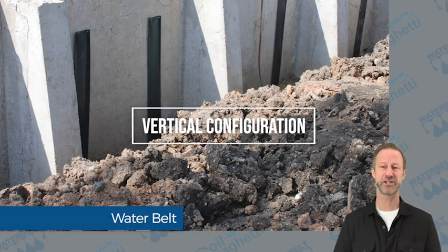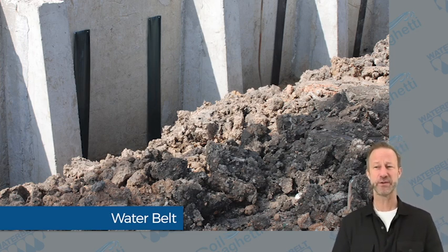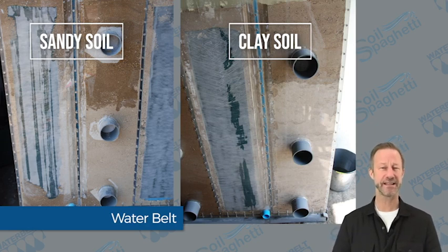Another popular installation method is the vertical assembly. Belts are installed vertically, leading into a pipe running horizontally along the footings. This is an ideal installation for behind retaining walls, or placed around the outside of buildings to prevent hydrostatic buildup against the walls. Any water buildup against the wall is immediately collected by the belts and transferred to the pipe below and discharged. Testing in both sandy soil and clay shows Waterbelt starts to work as soon as water comes in contact with the surface of the wall.